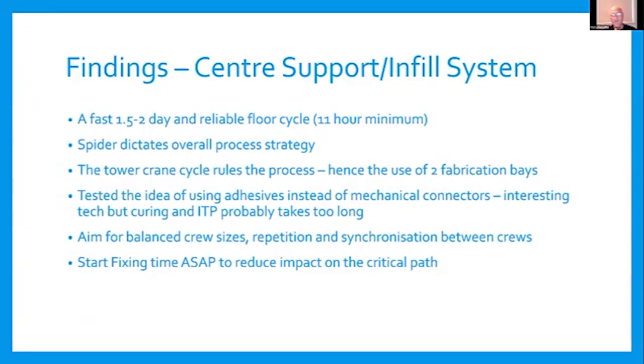We tested, I didn't mention it before, using adhesives instead of mechanical connectors between the panels, which is really interesting technology. But I think for practicality, the things that affect it are the curing time. So, for example, if you have to wait 2 days, which was the sort of typical time to get around 80% strength, that's just added onto your floor cycle because you can't start your next one.